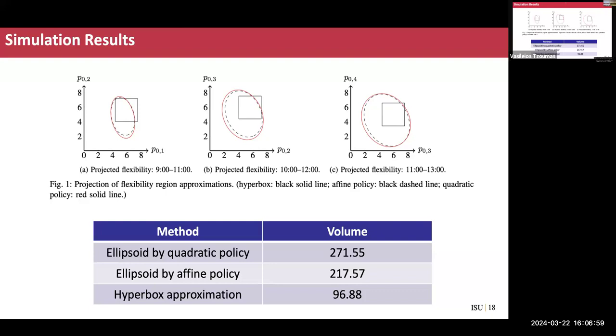The main reason is that we have tight bounds on the voltage constraint, maybe plus or minus 5%. Within this range, this linear approximation works really well. For larger variations of power and voltage, we may enter the nonlinear region of the power flow equations. But within this tight voltage bound, the linear approximation works really well.